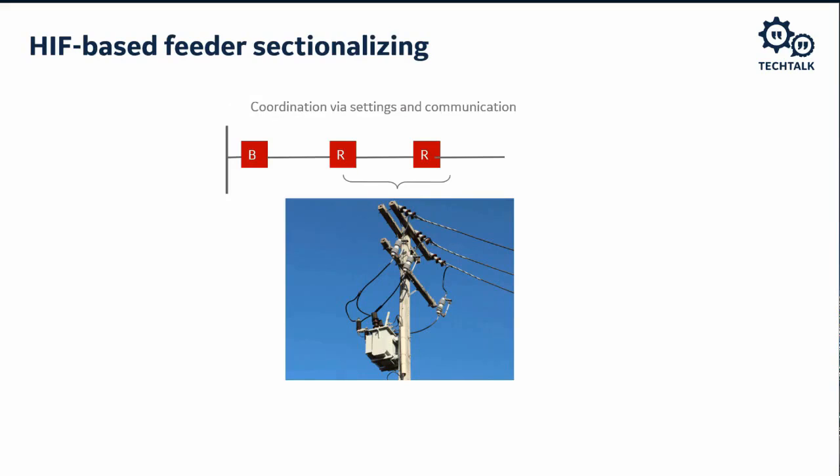One popular application is sectionalizing the distribution system when an arc occurs. Upon detecting serious arcing or a down conductor, the closest recloser controller senses the arc and disconnects the line before a fire can start. This is a one-shot trip and lockout sequence.